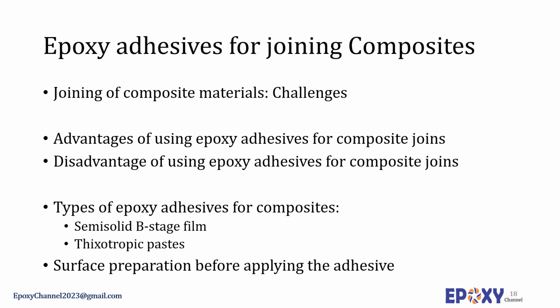To bond large composite structures, room temperature curing adhesives are preferred. Employing room temperature epoxy adhesives, expensive fixture tools and curing equipment required for higher temperature cure adhesives are eliminated. However, room temperature epoxy adhesives are not suitable for large, high-speed production runs as their curing time is long.